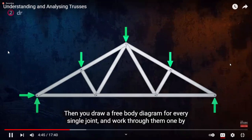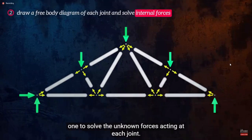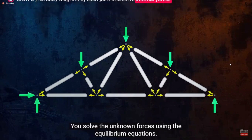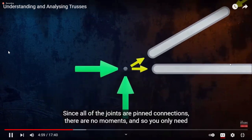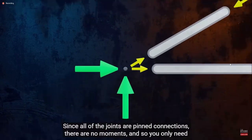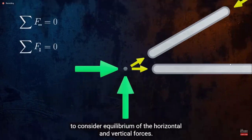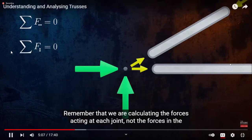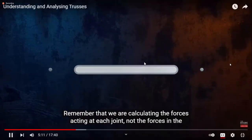Then you draw a free body diagram for every single joint and work through them one by one to solve the unknown forces acting at each joint. You solve the unknown forces using the equilibrium equations. Since all of the joints are pinned connections, there are no moments, and so you only need to consider equilibrium of the horizontal and vertical forces. Remember that we are calculating the forces acting at each joint, not the forces in the member.